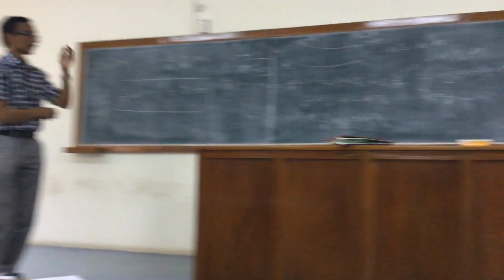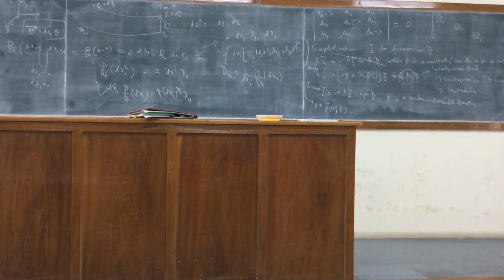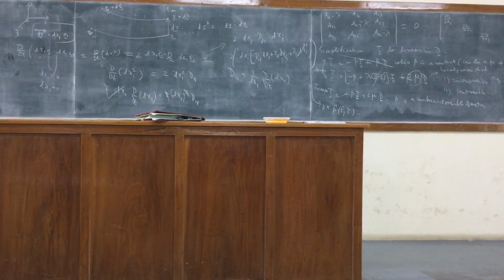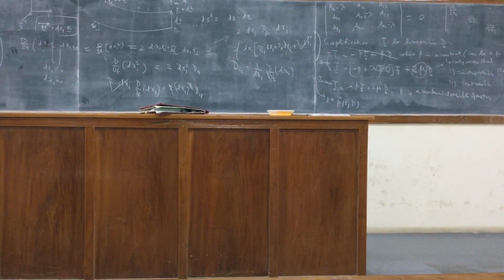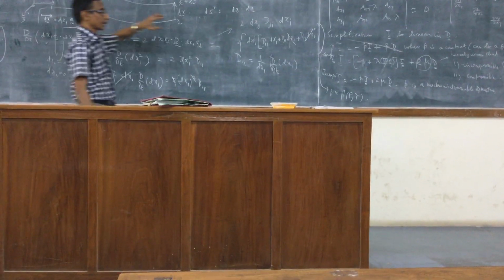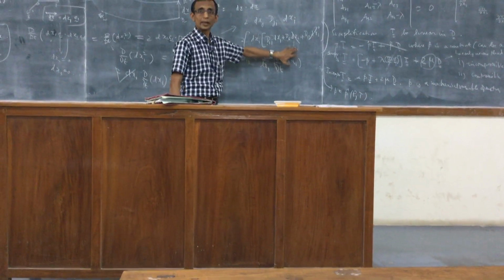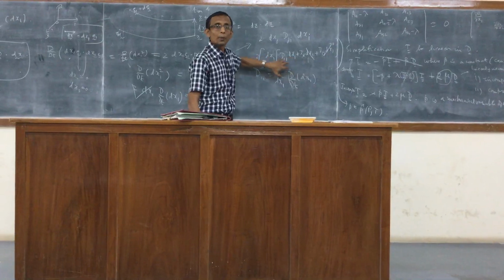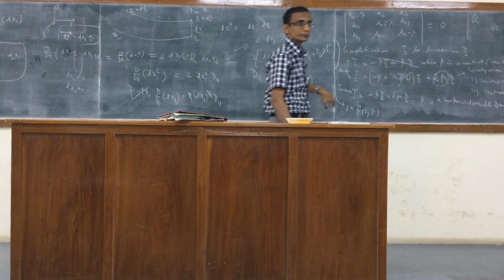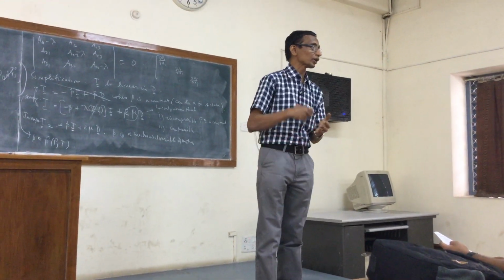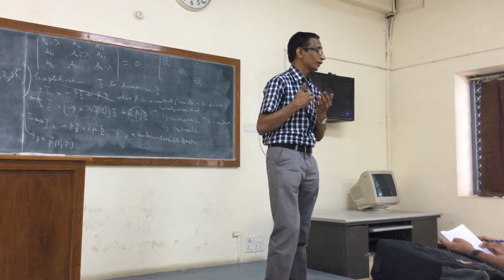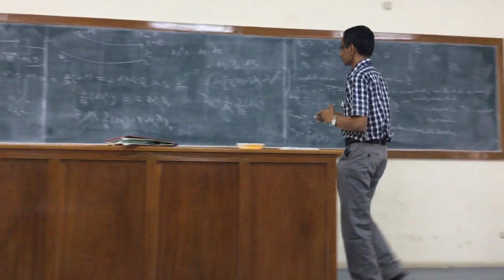So what can you say about the right hand side? What does it represent? Because the length here is only dx1, this is the time rate of change of the length of that element per unit length. So that is why the deformation tensor is often referred to as the rate of strain tensor.